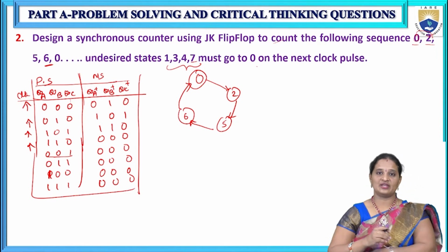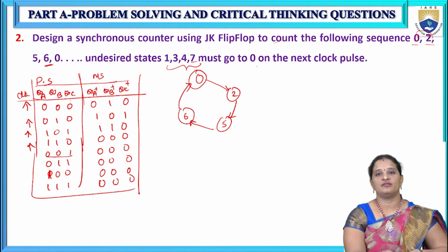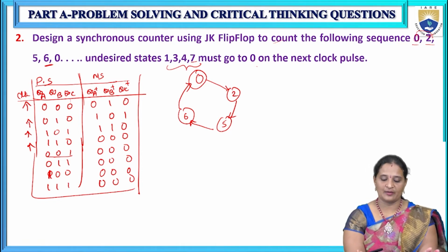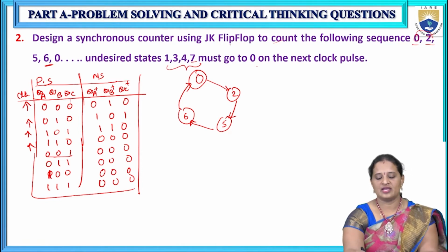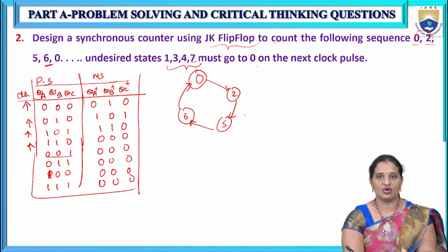So, a state table represents the next state of the counter by considering the present state value, right? Now, as he has mentioned, once the table has been prepared, we need to identify the proper flip-flop. As already mentioned, we need to design this counter using JK flip-flops.